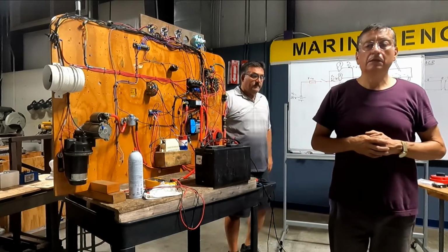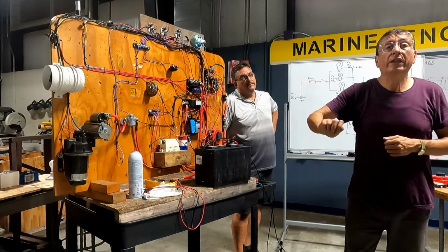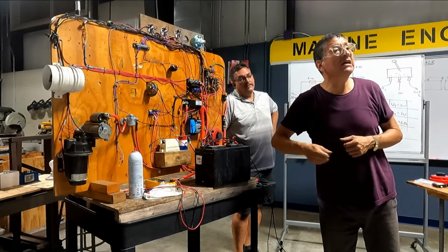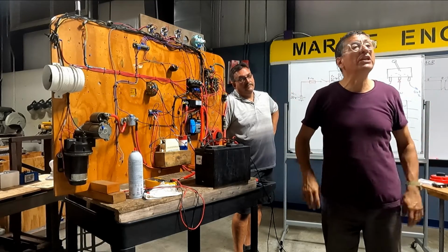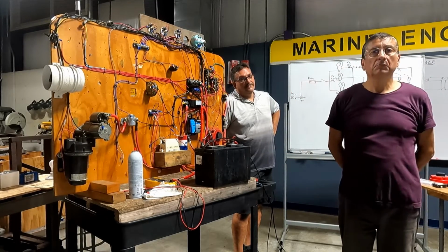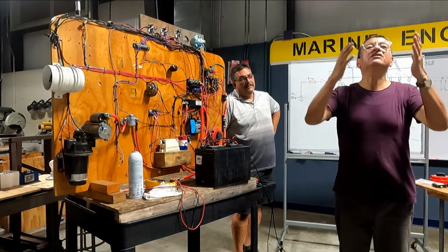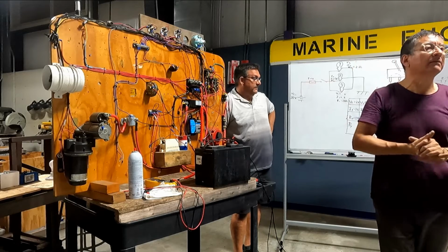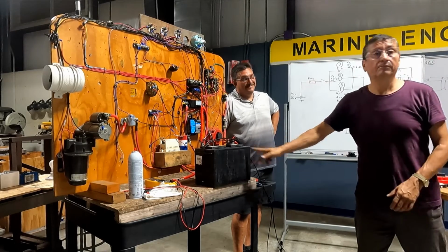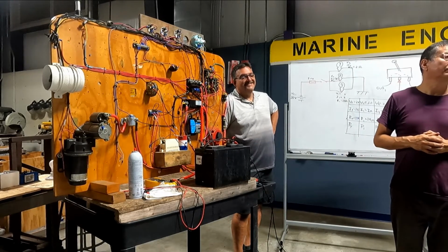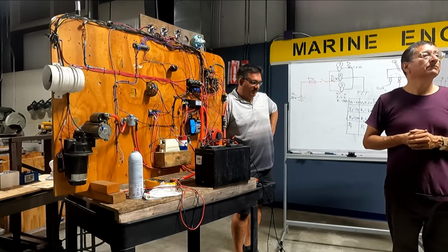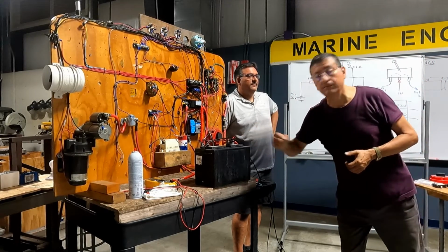The customer says, when I try to start my engine, the engine is doing nothing. Nothing. And you hear a click? No clicks, nothing. Okay, what is the first step in that scenario? Check the battery. How do you check the battery? Load tester. Okay, I have power in the battery.